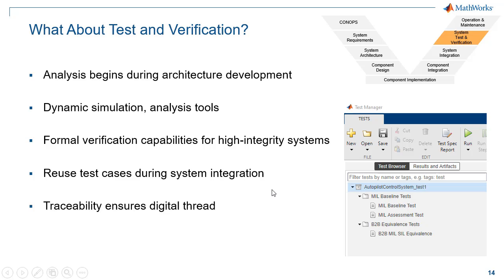Those tools work not only with model verification, but they often have tie-ins with code verification. So you can reuse those test cases that you built up with Simulink Test and begin to run them on processor in the loop testing or even hardware in the loop testing. We do everything we can, again, to help you find those errors earlier in the development cycle through continuous test and verification.